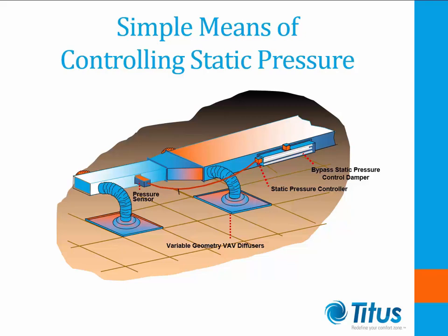The pressure in the duct can be controlled using face and bypass dampers or if carefully selected, a bypass damper only. The face damper will allow enough air through to maintain the required pressure in the ducting. The bypass damper will bleed off excess pressure to the return air side of the air handling unit.